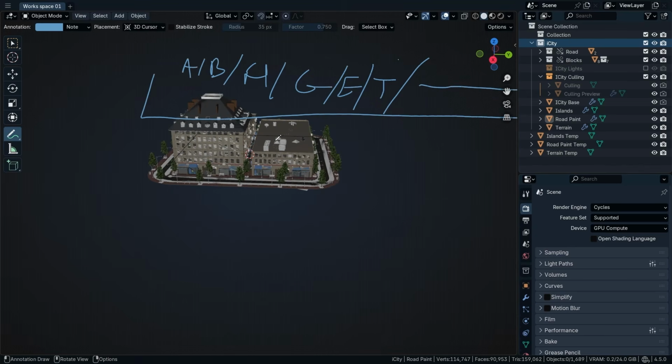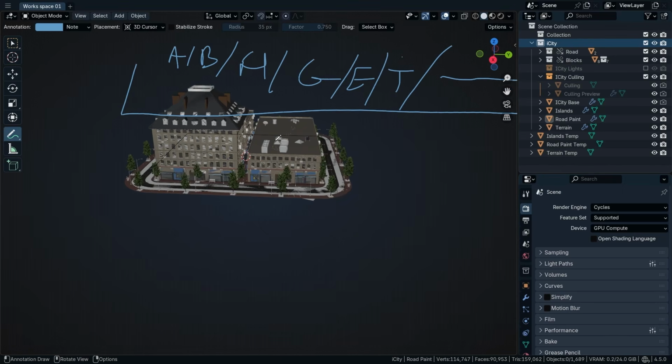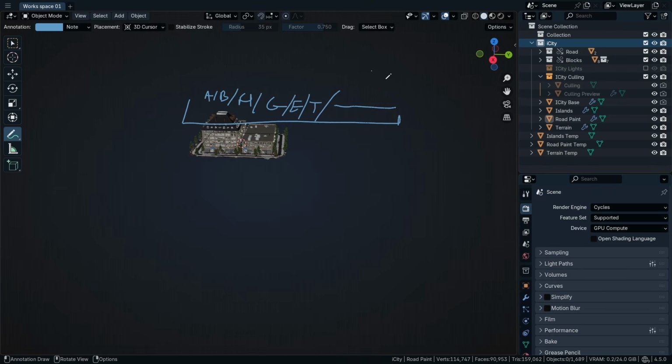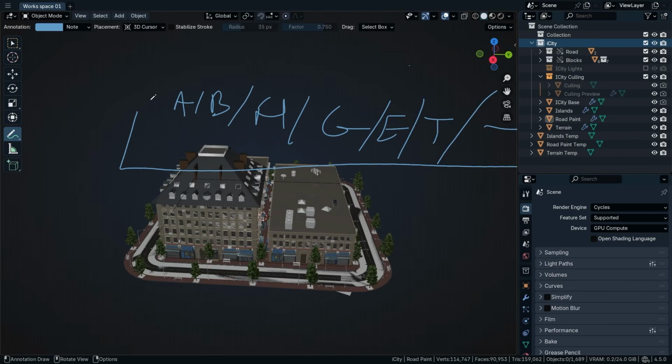And when using any add-on in Blender, when it wants to extract the zip file, I think there's a maximum of 200 characters. Anything more than this is going to give you the installation issue. Okay, so why does it work on some devices and on other devices it does not work?